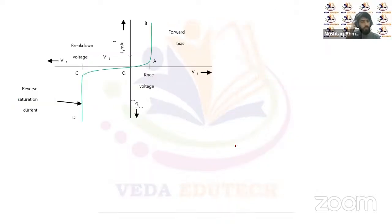Now, combining both the graphs for the forward biasing and the reverse biasing. So this is how it will be for the forward biasing and this will be for the reverse biasing, right? Now, this voltage we call the reverse breakdown voltage, right? At this voltage, the current because of the minority carriers increases exponentially because of the breaking of the bonds within the material, right? And this current we call the reverse saturation current, right?